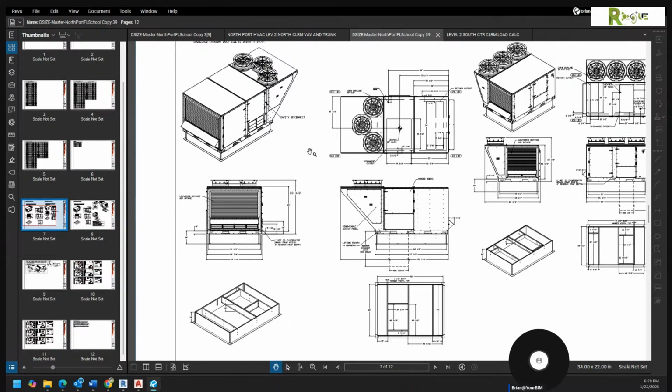They don't ever identify how important it is how an architect declares his walls are fire rated. Because if he's not real careful on how he does that, the MEP trades can't even tell where fire rated walls are. It's very difficult. So I think people lost the point with the LOD 400.